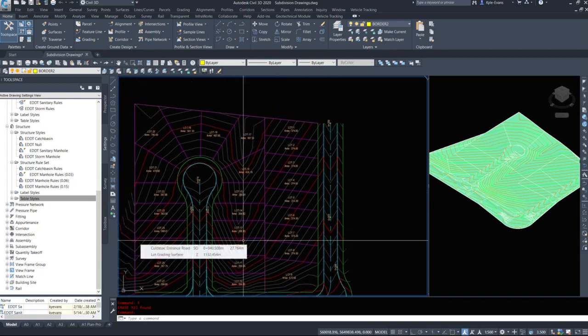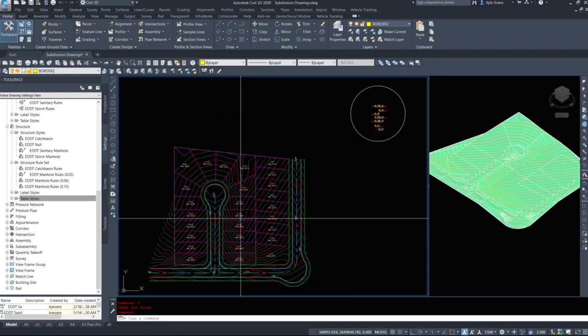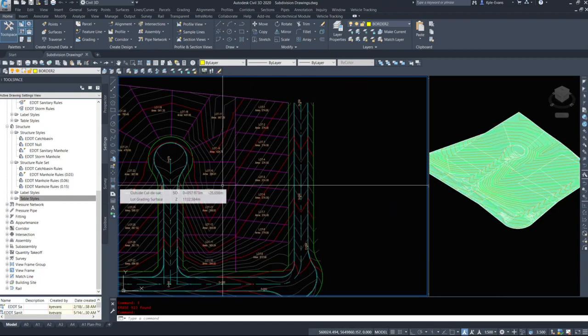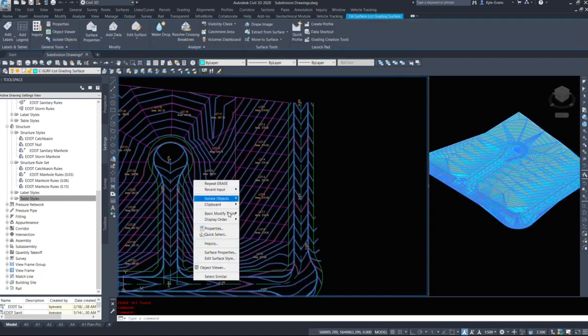Now, when we're trying to figure out where our groundwater is flowing or where the rainwater is flowing, in general, where I design, a catch basin can only handle about 1 hectare of land area before we have to put in either a double catch basin or split the area up. Because we have a constrained pipe size, we can only fit so much water into that catch basin itself. So there's a couple ways of doing this, figuring out where your water's flowing.